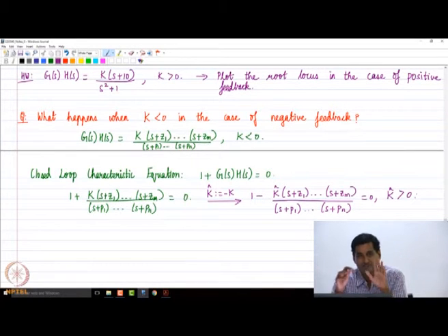Physically the original system is negative feedback, but this is basically a pseudo positive feedback system with a positive gain k hat. You follow the same steps that we learned today in the case of positive feedback and positive gain. You repeat the same steps, determine the answers for k hat, then your root locus will be the same. But then whatever answers you give for stability and performance, you change the sign, so that when you quote in terms of values of k, it should be minus of k hat. That's all you need to do when you want to go the other way. So is it clear?